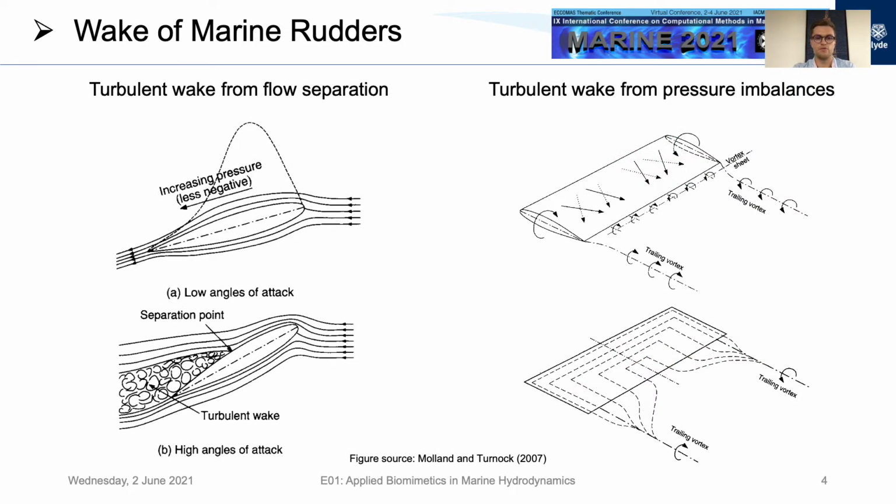There are a number of wake effects that can be reduced by the tubercles. Tubercle leading edges confine flow separation to the areas behind the troughs, which could minimize the chaotic turbulent wake that forms as a result of separated flow for a conventional hydrofoil. The tubercles also minimize spanwise flow.